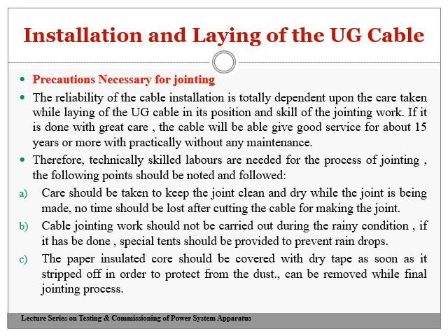Cable jointing work should not be carried out during rainy conditions. That is important, because when you open up a trench, the water gets into the trench, and it may cause further damage to the other cables which are already laid there. That's why jointing should be avoided during the rainy season. But sometimes it is inevitable and essential. At that time, much care should be taken for jointing in rainy conditions.